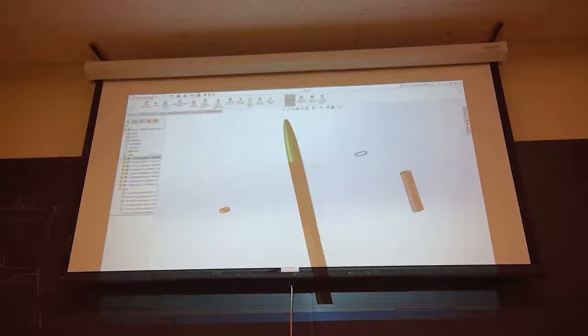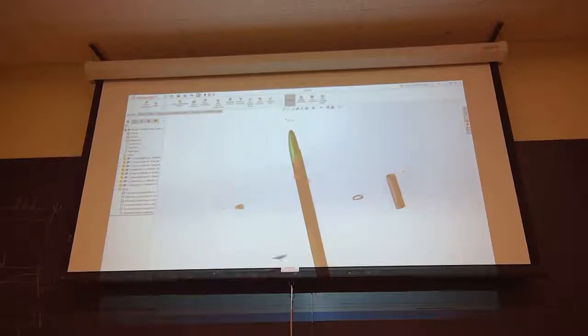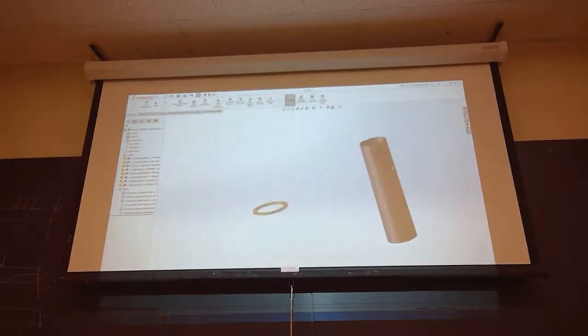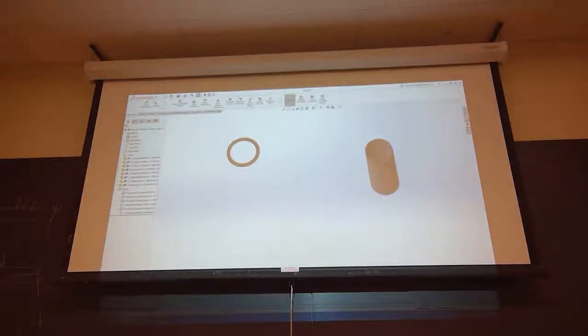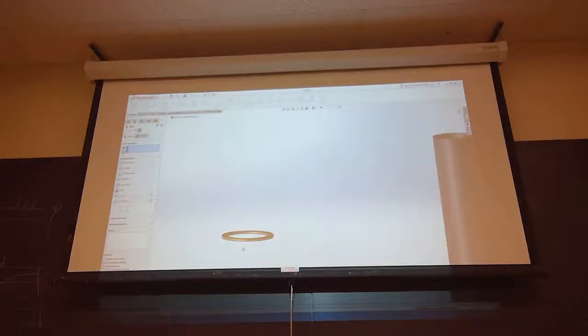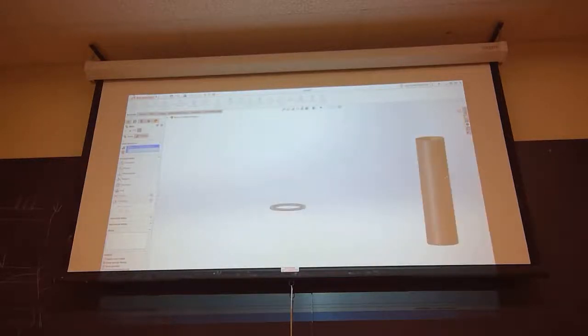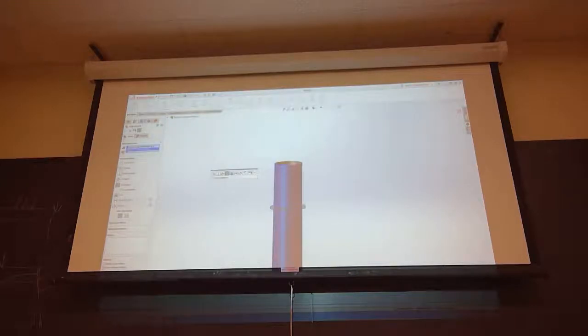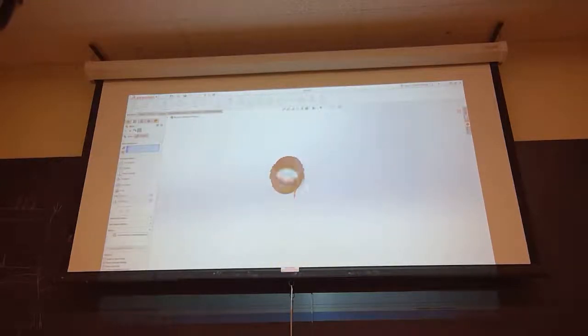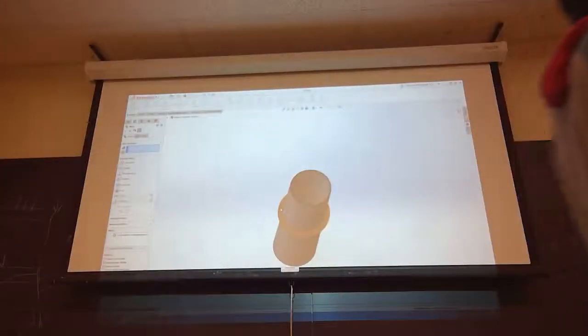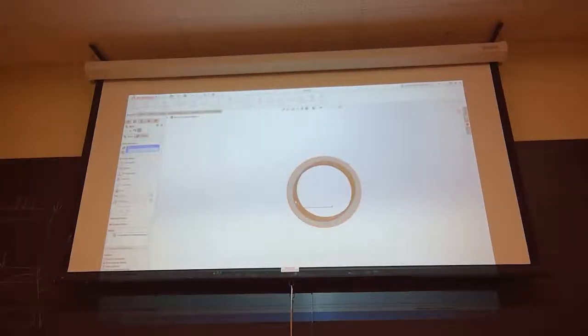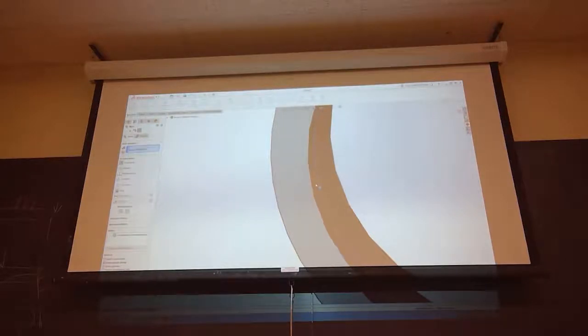But if yours can already move, then that means it wasn't the first one in the part. Not an issue. We're going to do another distance mate on this one. First thing is, we want to make sure it's concentric as usual. Same thing we've been doing all night. Go ahead and make these 2 concentric. Now, 6 inches, right? We're going to take this and distance mate it to the top at 6 inches again.